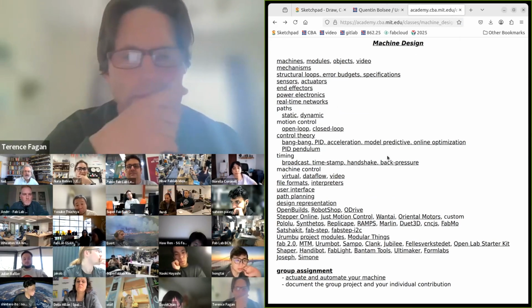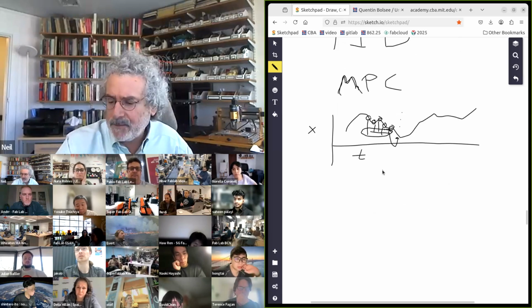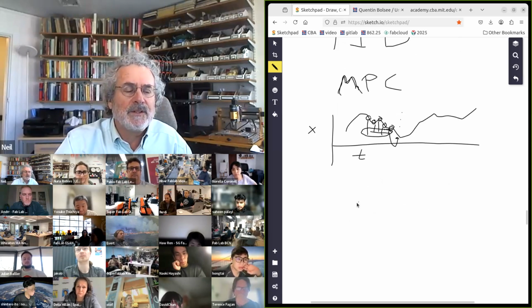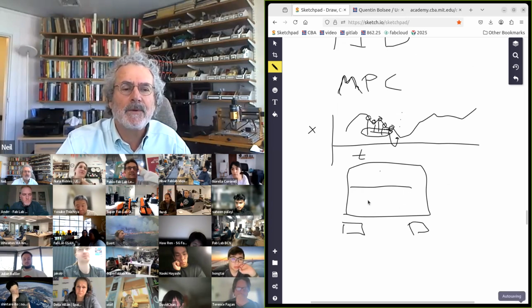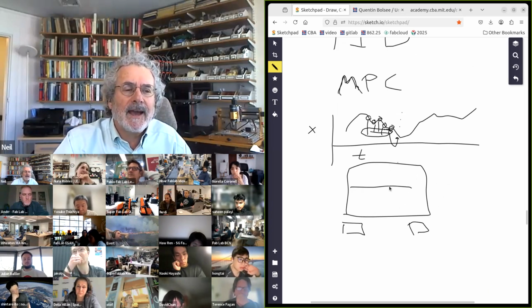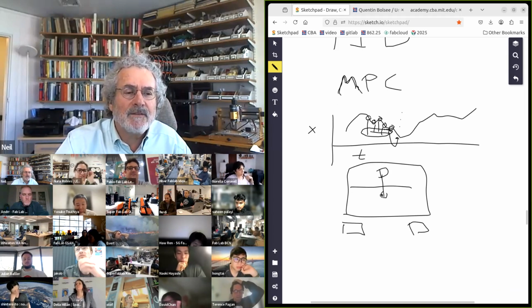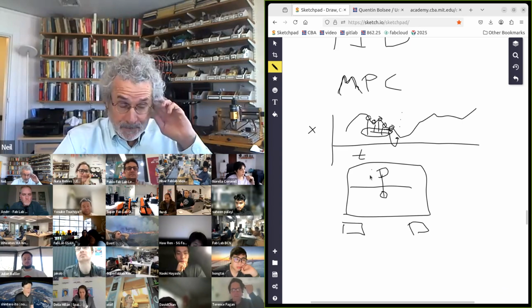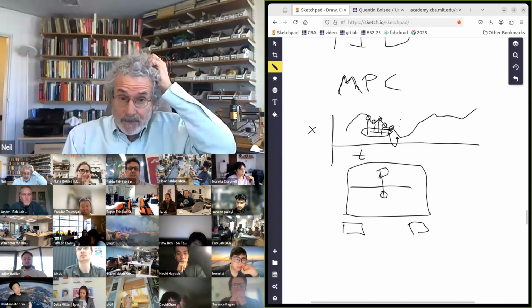So then, let's see, if we just start already with the core XY, in the core XY, we have two motors, and then we have our core XY. But then we might have a core XYZ where there's another motor controlling the Z axis. And then we have an end effector that might be a spindle. So we've got multiple degrees of freedom and we need to coordinate them.